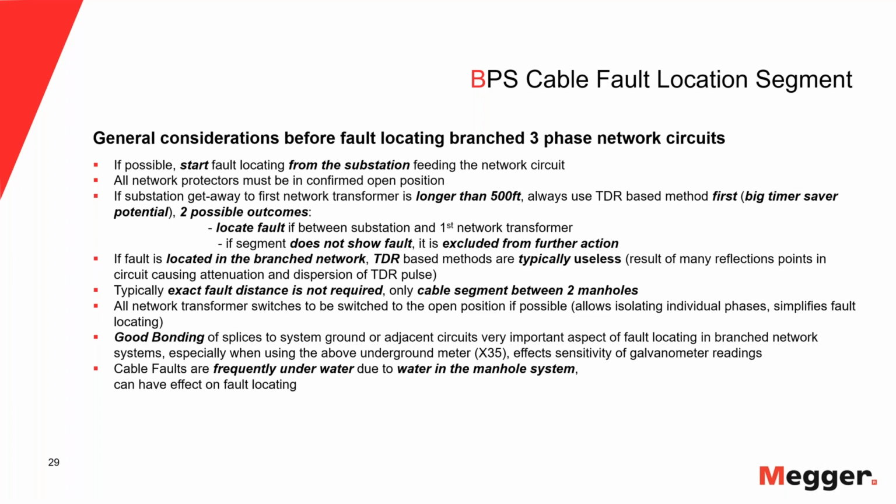I always say, maybe in 20% you're lucky, because if you just happen to have the fault pretty close to where your connection point is, you will see the fault. But this is not a method that is typically used. On the other side, to just try it takes you maybe 2 minutes to see whether you see something that looks meaningful. If it doesn't, you move on and you do whatever you do normally. Okay, so there's nothing lost. There's only something to be gained, because if you see the fault, the time savings is tremendous compared to a traditional fault locate in the branch network.